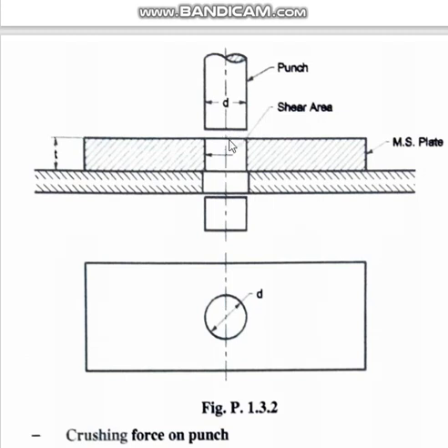Then what you are left with is a punched sheet or punched plate. Now here there are two things. One thing is your punch may fail. How will the punch fail? Suppose you are hitting it against this surface, and this surface is very hard, so you cannot do anything to this surface. Then this thing may get crushed.